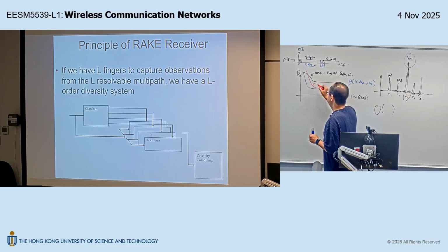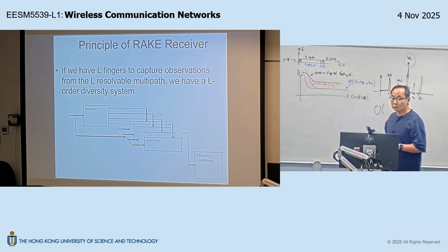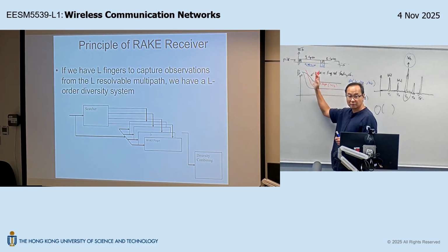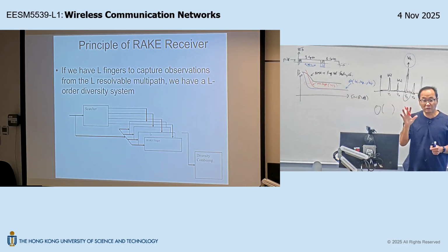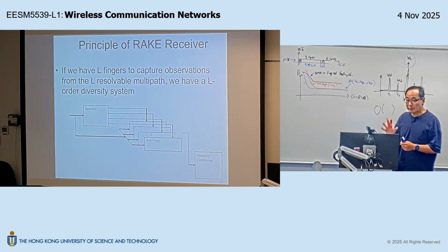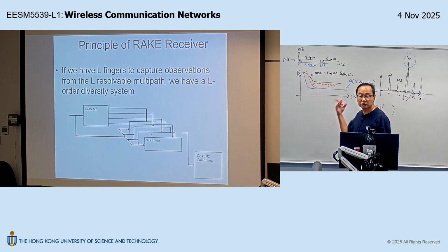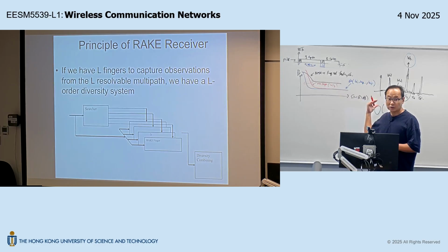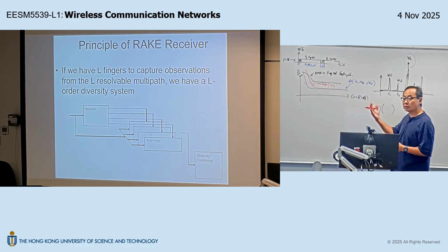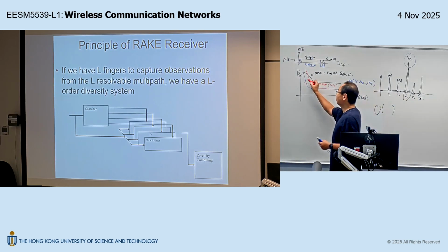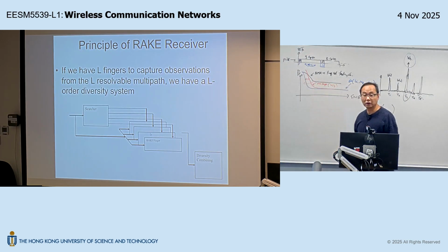So this is with one finger. In this example, despreading on W3. You notice that the slope is the same. So you get the same diversity order as if you have five despreading fingers. But you suffer from a penalty. The penalty is, since you're doing selection combining here, the signal-to-noise ratio is not the same as having 5 fingers. So you lose out 5 times of energy. So you have a horizontal shift. Okay? But the diversity benefit is the same.